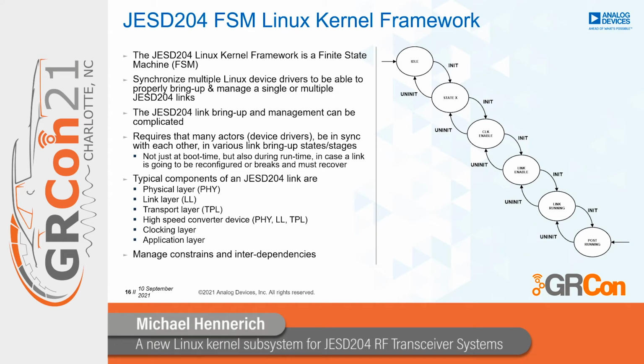Like mentioned before, a link establishment is a sequence of finite steps. Thus, the Linux kernel framework is a finite state machine. Its purpose is to synchronize multiple Linux device drivers to be able to properly bring up and manage a single or multiple JESD204 links. Link bring-up management can be complicated because it requires many actors, device drivers, to be in sync with each other in various link bring-up and setup stages. That happens not just at boot time, but also during runtime in case a link is going down or needs to be reconfigured, breaks, or needs to be recovered.